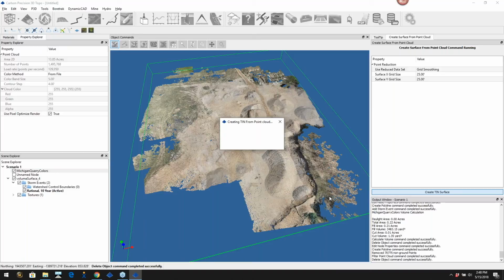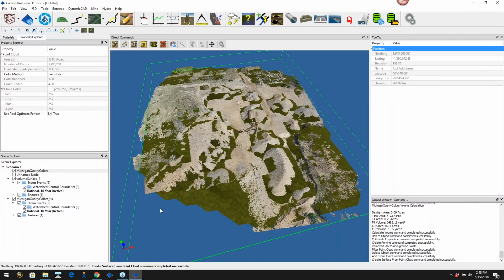And we did have one question on here that asked if there is a report given on the accuracy and precision of the photogrammetric analysis in PhotoCapture? And the answer is yes. So one, there's a bundle adjustment report that's very detailed. And then also at the end, you'll note there's a project report that is full of all your statistics from the bundle adjustment itself and the accuracy.